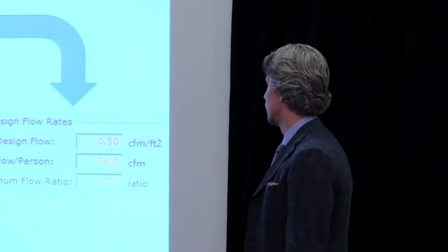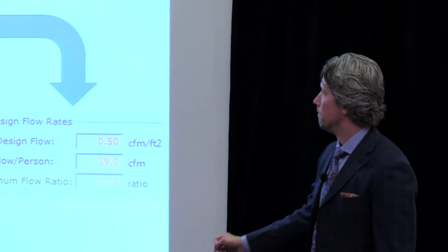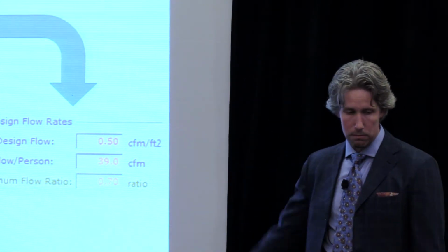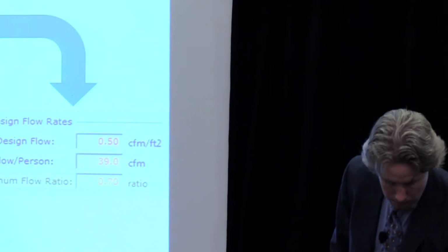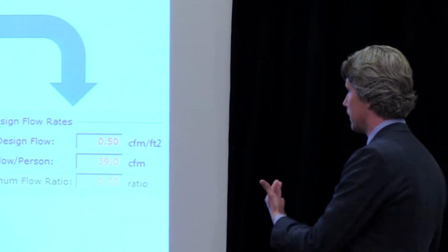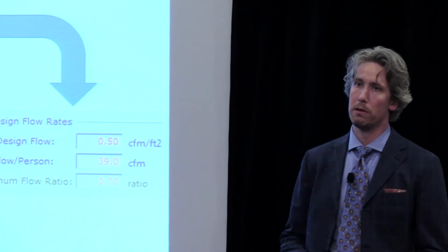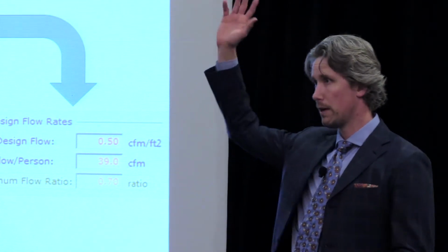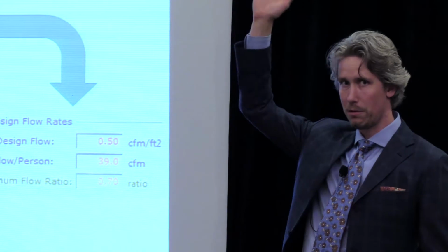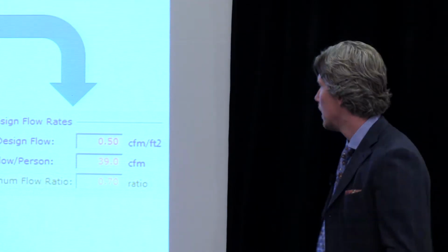So I'm going to start with a real easy one. This is a building where we're doing a retrocommissioning project, and we found VAVs with the dampers stuck wide open, right? So they didn't modulate. Who's seen a VAV with a stuck damper? And we probably all have.